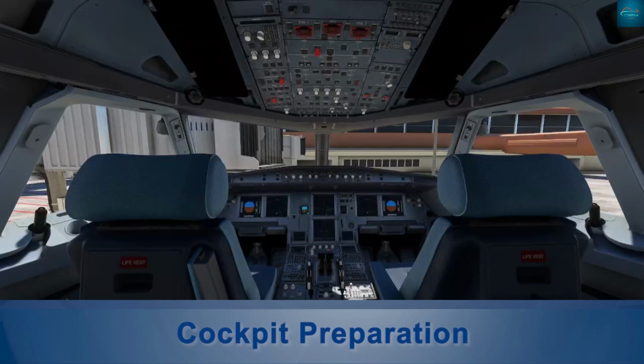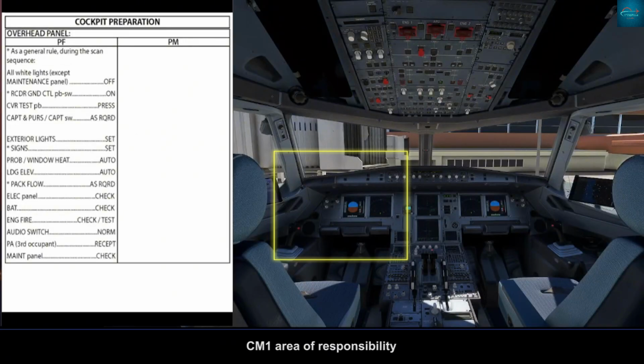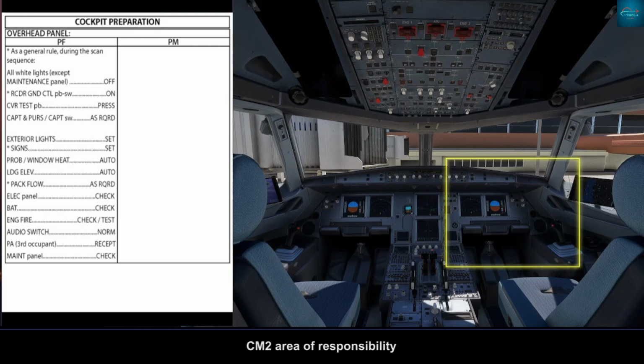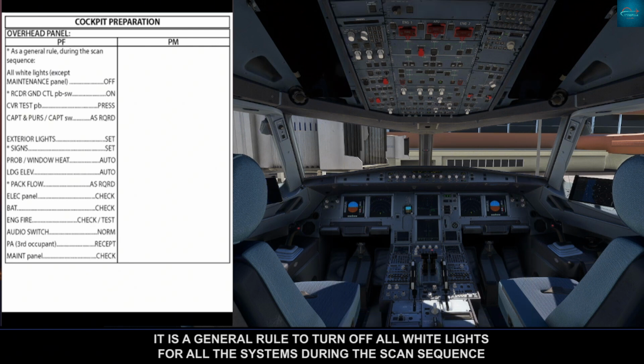A320. Cockpit preparation. Panel scan sequence. CM1 area of responsibility. CM2 area of responsibility. Pilot flying area of responsibility. It is a general rule to turn off all white lights for all the systems during scan sequence.